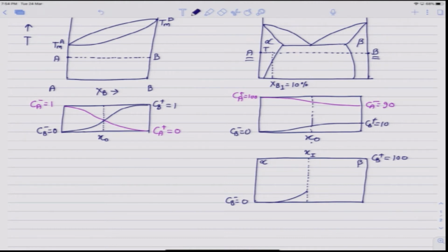Now, there are two sides for the interface. On one side there is phase alpha, on the other side there is phase beta. If we want to determine the equilibrium compositions at temperature T in the 2-phase region, we draw this tie line, which I have already drawn here, and I mark where the tie line intersects the 2-phase boundaries. So, this tie line intersects at position A and B here, and A represents the maximum solid solubility of B in alpha at temperature T.